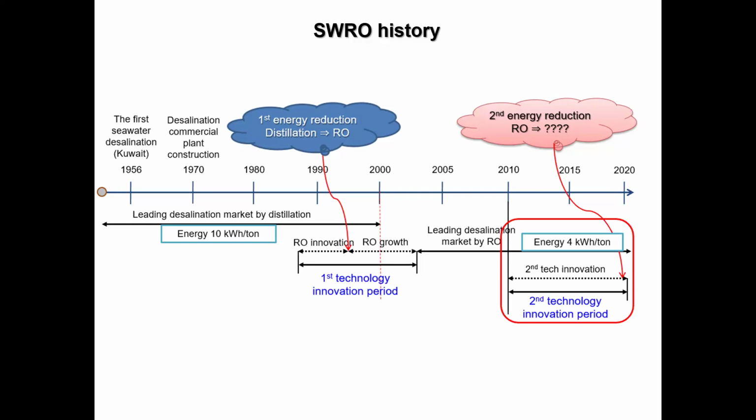You pressurize the RO, so the leftover pressure you exchange again and apply again at the RO. Pressure exchange was developed in the 1990s. And we decreased energy cost by more than 50%, which means now it's around 2 kilowatt hour per cubic meter. So the second innovation, pressure exchanger. We discovered it 30 years ago. Since then,